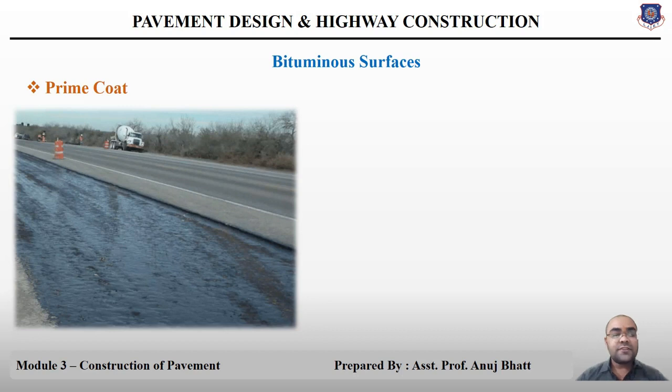So this is a surface with a prime coat. Let's discuss something on the prime coat. When a bituminous surface has to be laid on an absorbent or porous surface such as water-bound macadam, then a bituminous prime coat has to be first laid prior to laying the superimposed layer.